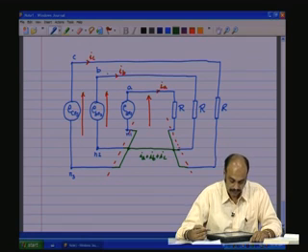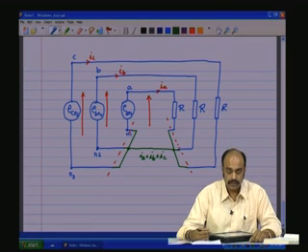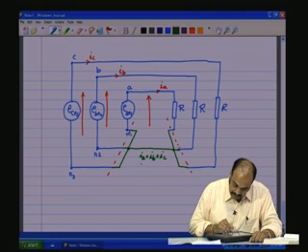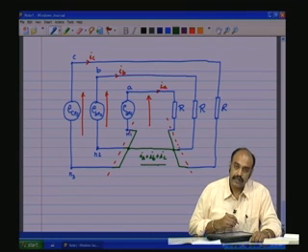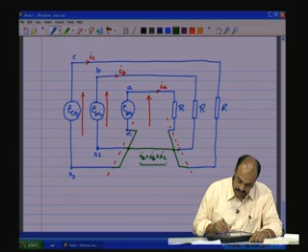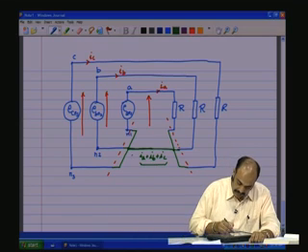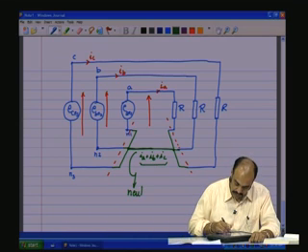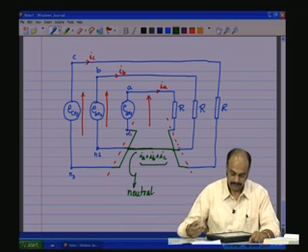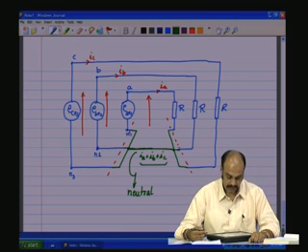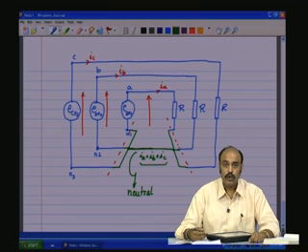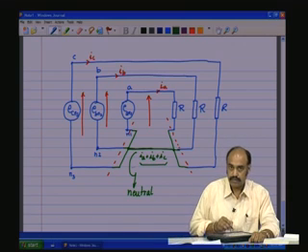How do they look like, and what is the instantaneous values of these 3 put together, and what is the resultant current which flows through this line, the return path line, and this line is called the neutral. This is called the neutral line. The return path line, which is common, is called the neutral line, through which IA plus IB plus IC flows.